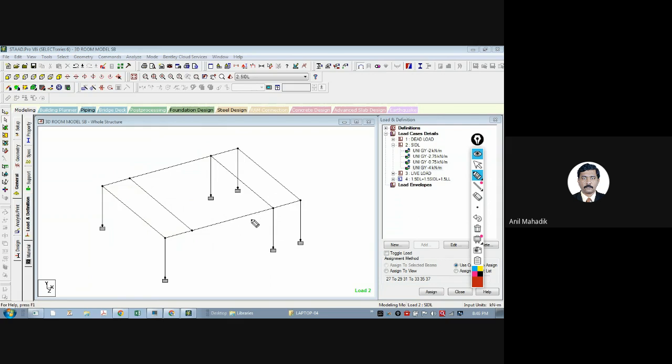We have a lot of balconies, staircases, one-way slabs, two-way slabs, different rooms, living rooms, so the plan is generally complex, and putting all the X range, Y range is really difficult in Staad Pro for complex building shapes. But in ETABS, just draw the slab and put the load. That's it. It will take care of the distribution of loads, one way, two way, and everything. But as a matter of learning, you should know how to do it. As to which software you want to use for buildings or other structures, it will be your choice as per your convenience.